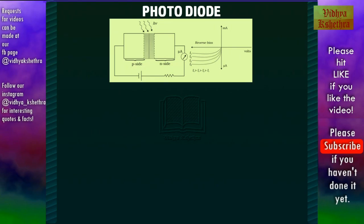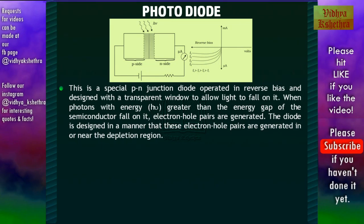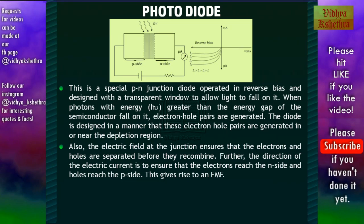Now we can see about optoelectronic devices, and the first one is the photodiode. This is a special PN junction diode operated in reverse bias and designed with a transparent window to allow light to fall on it. When photons with energy greater than the energy gap of the semiconductor fall on it, electron-hole pairs are generated. The diode is designed in a manner that these electron-hole pairs are generated in or near the depletion region. Also, the electric field at the junction ensures that the electrons and holes are separated before they recombine.